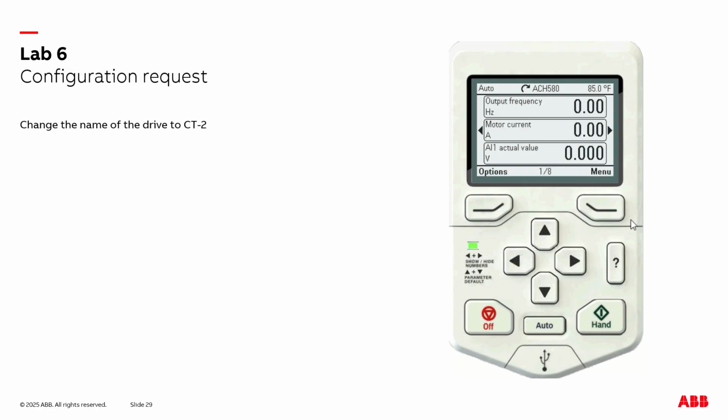For Lab 6, we're now being asked to change the name of the drive that appears on the top middle of the screen, which defaults to ACH580, to instead say Cooling Tower 2. Now, if you want to pause the video here, please do so now if you want to practice doing this on your own, and I'll show you how to do it.